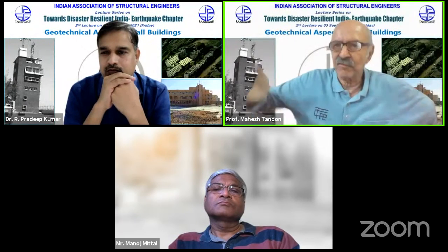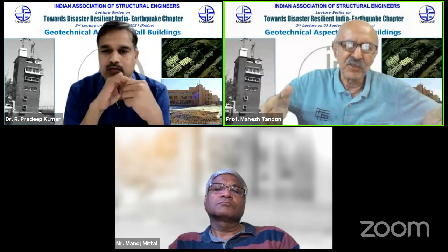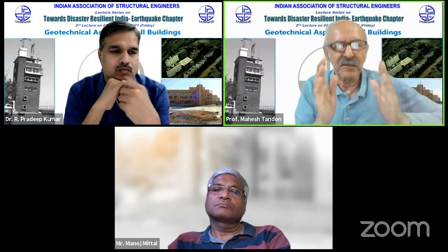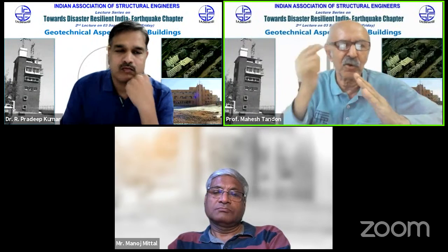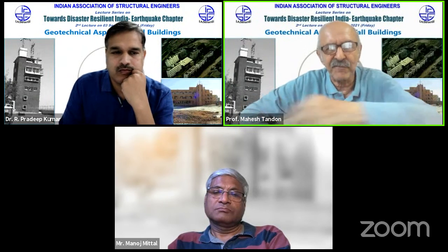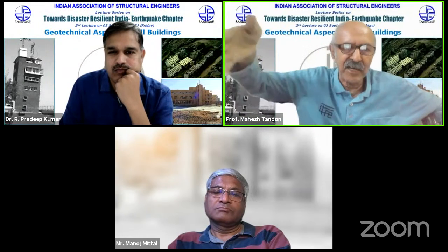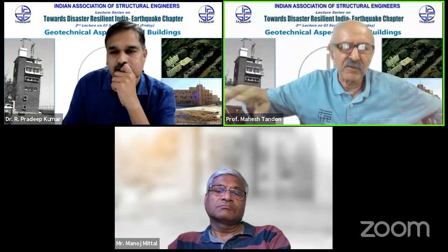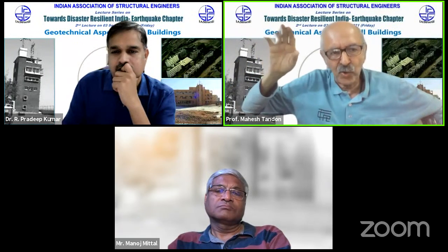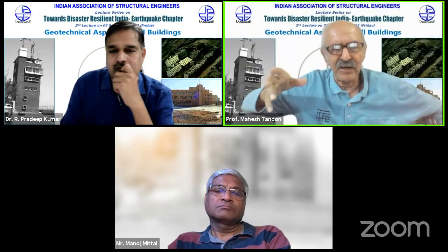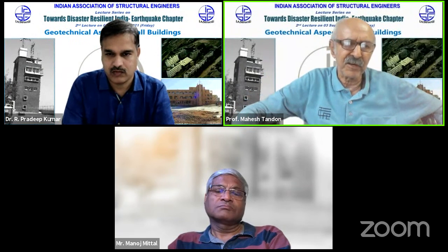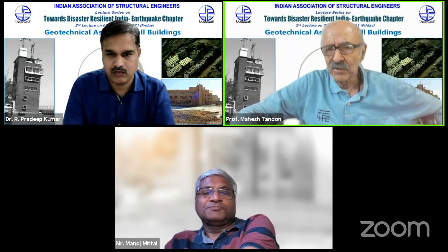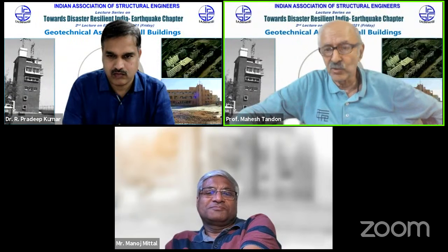For example, in the old days, we used to put the load on the side. If the well has tilted, you put the load on the other side, much like what the San Francisco fellows have done. They are trying to put piles there. Instead of piles, we put load on top where we want it to go down. So it's something similar which you have to do by means of rectification. And like I said, there are many case studies which are available as to how to do it.